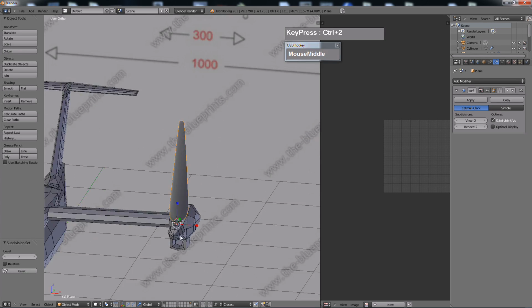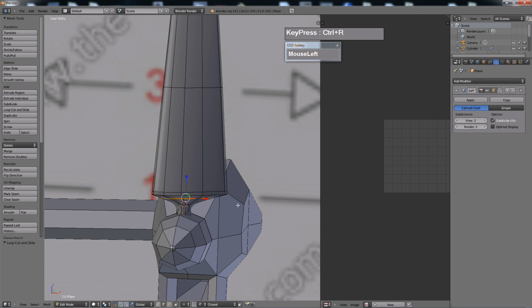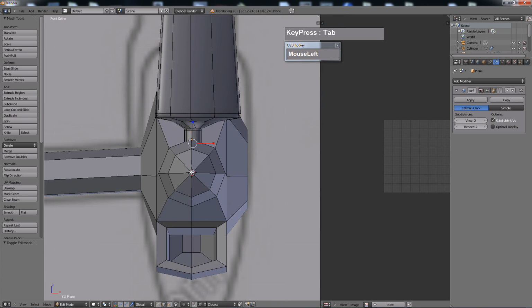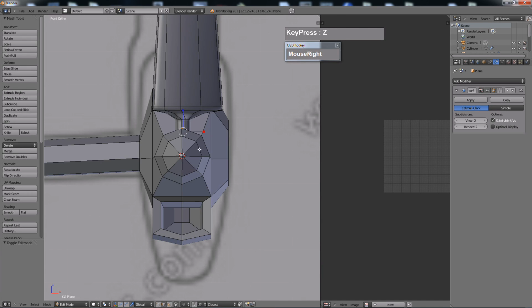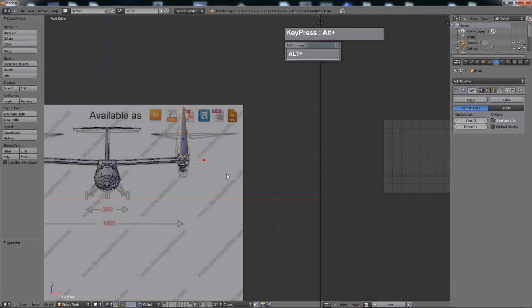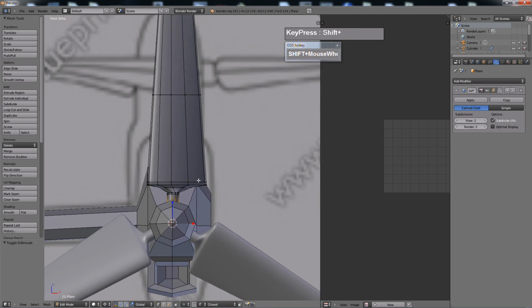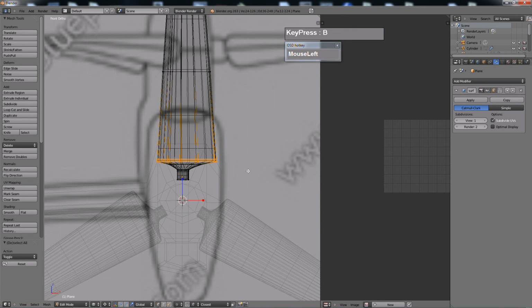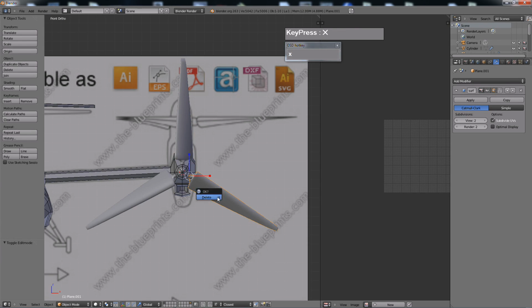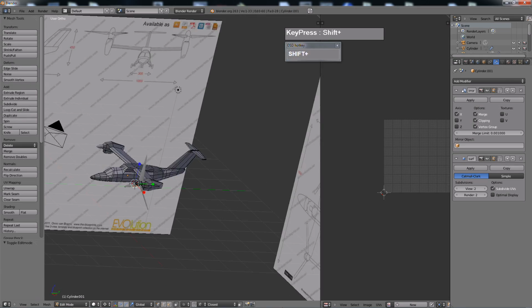And over here I'm doing some tweaking to the propeller blade, and after that I apply a smooth and a subdivision to it to see what the smooth propeller blade looks like. And later I decided that the width of the propeller blade is too big, and I will actually reduce it. Now you can actually use Alt-D to create a duplicate reference. So if you modify the original mesh, the duplicates will actually change along with it. Okay, so apparently I think I pressed the wrong command, so when I changed it, the duplicates did not change.